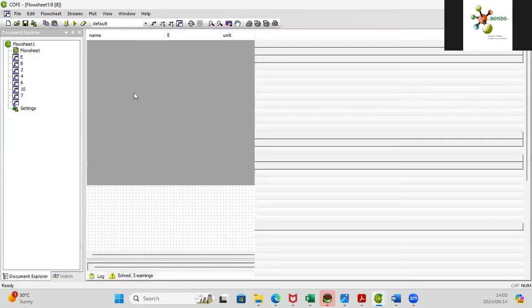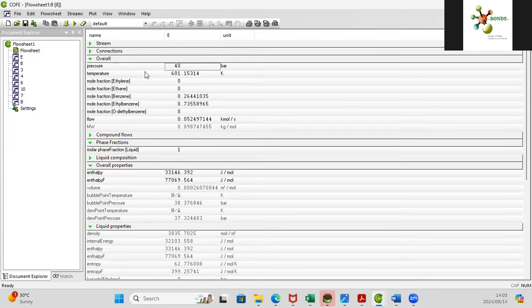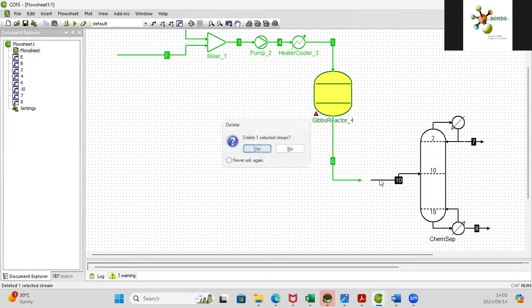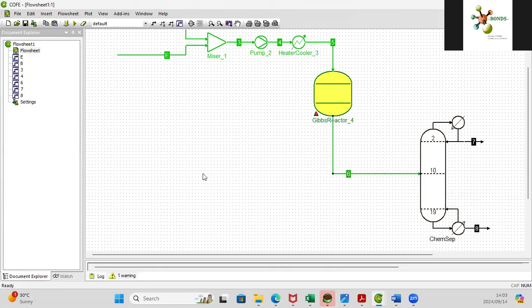And your bottom product will still have some benzene, but it will mainly be your ethyl benzene. So what we can now do is remove our cheat, because COCO has now built that pathway into your simulation, so your column now knows how to separate. Hopefully, now that you've removed it, it's going to be able to assign everything to where it's supposed to be.